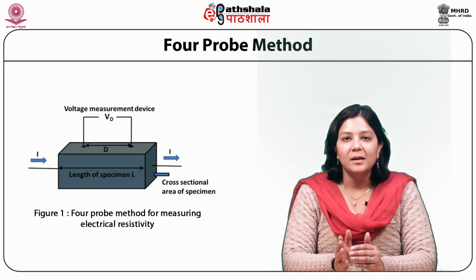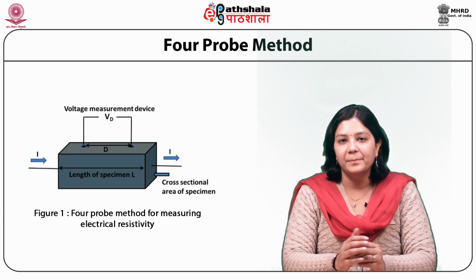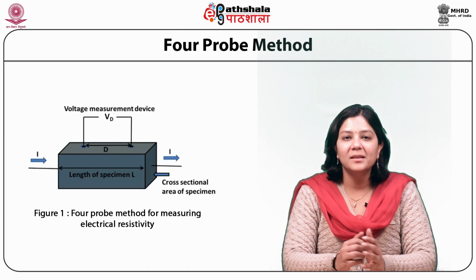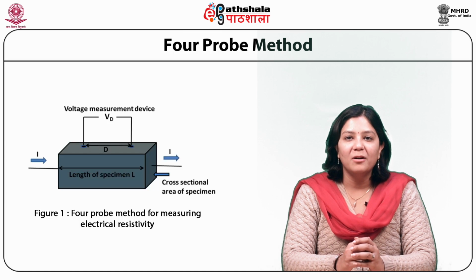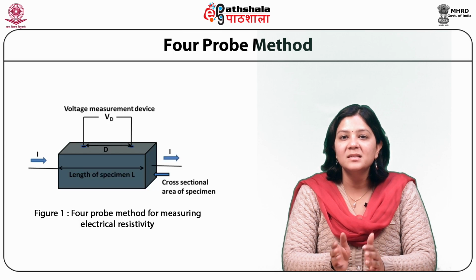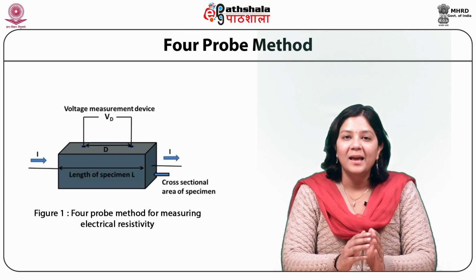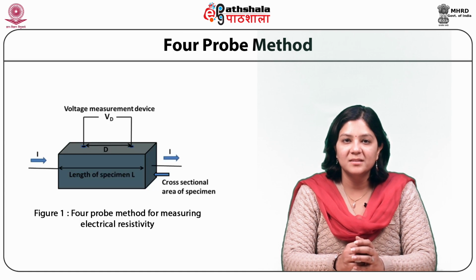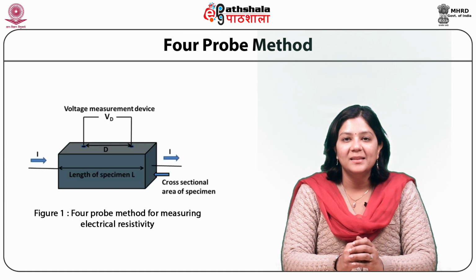The probe method equally applies to single crystal or bulk samples and can determine their resistances. Current flows through outer contacts near the sample edges and the potential difference is gauged across inner contacts. Hence, the effect of interfacial resistance between electrodes and sample is eliminated. Thus, it is a precise technique for low resistance measurements.